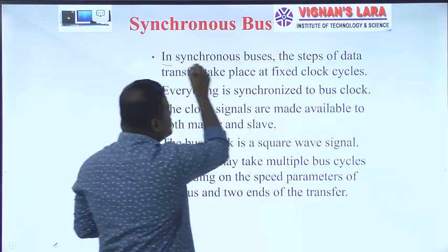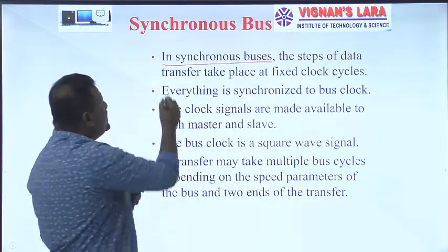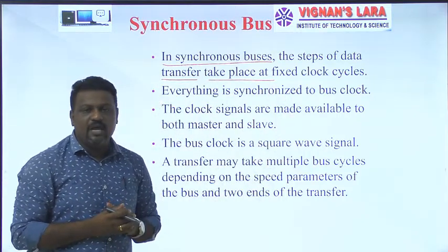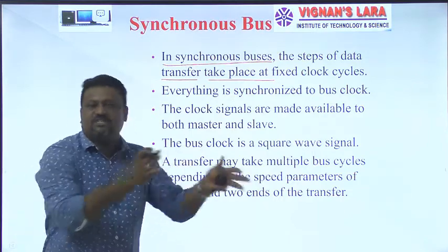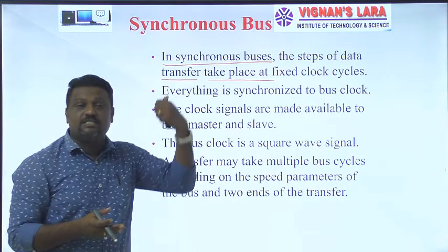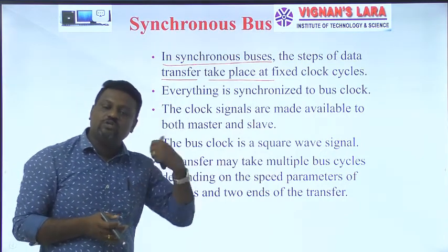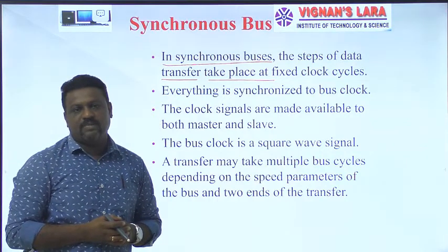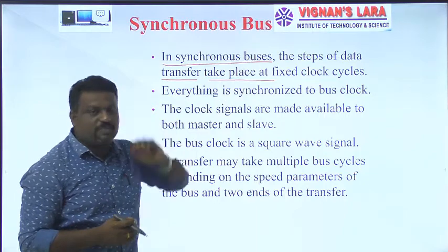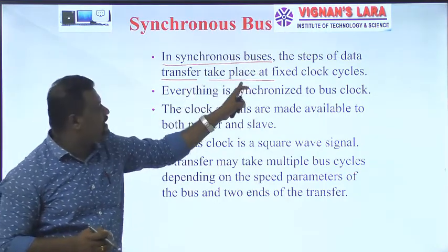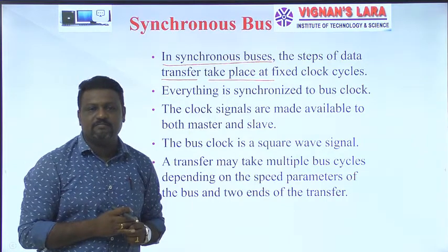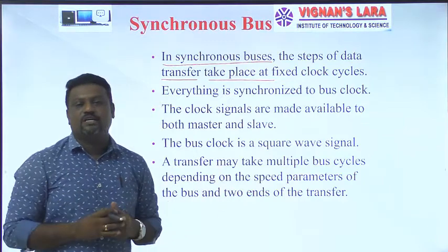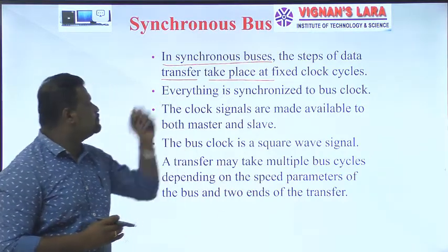That means in fixed clock cycles only is the data transferred between the two ends, in this synchronous data transfer scheme or synchronous bus protocol. I repeat once again, in synchronous buses, the steps of data transfer take place at fixed clock cycles. Only in fixed clock cycles is the data transferred between the two devices which are connected to the bus. That is the first point.